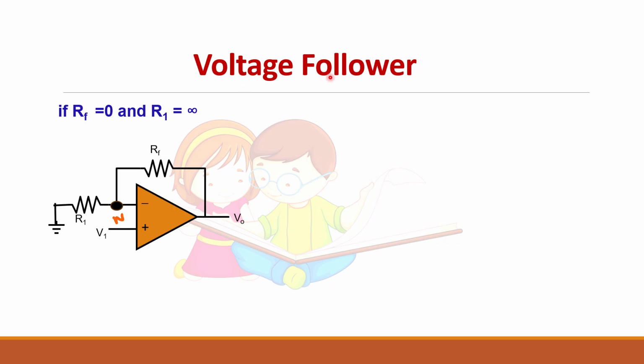Now we will see a special case of non-inverting amplifier, that is called a voltage follower. Suppose you have two resistors here, the feedback resistor RF. I am making this resistor 0. 0 means I have to short it, so let me short it like this. Then R1 I am making infinity. Infinity means it's open. The circuit is open.